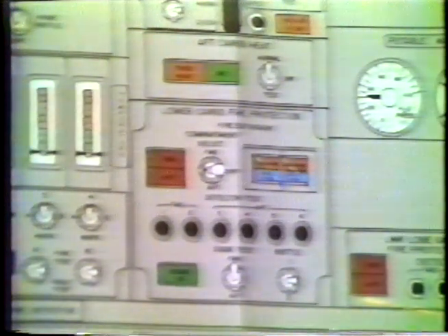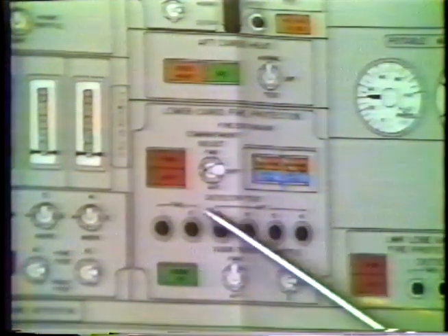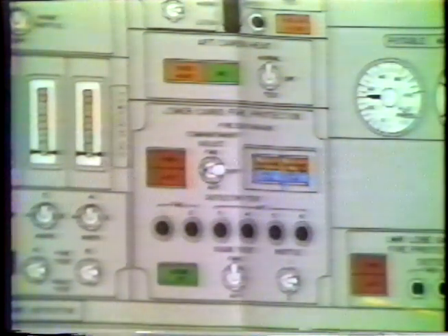One other point I'd like to bring up on the cargo: with the airflow through the airplane from front to back through the outflow valves, there is a good possibility that the smoke in the forward cargo area will find its way towards the outflow valves and eventually may give you an aft cargo fire. In this case, it probably would not be a good idea to fire the second bottle to the aft, because that's simply a result of the fire smoke finding its way to the outflow valves.